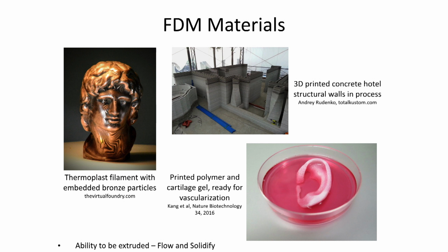However, in order to print things like ceramics or metals, we would have to extrude those into place and then bake them afterwards. So generally, for materials like that may be too high temperature or may not be able to travel in a liquid form to our build plate here, we might move on to some other technology, such as plasma deposition or laser sintering or electron beam sintering, or curing in the case of resins and thermosets.